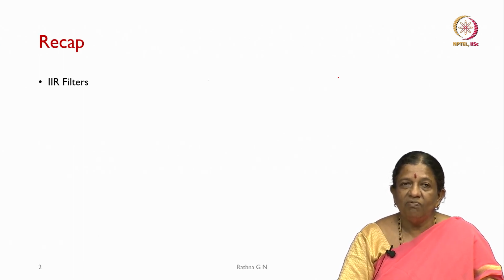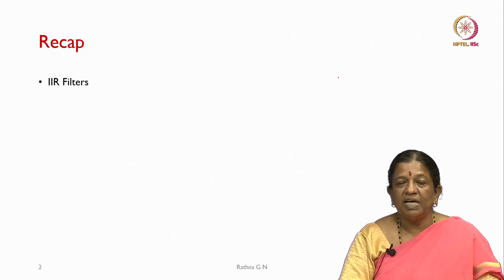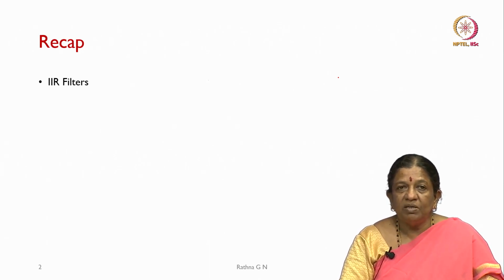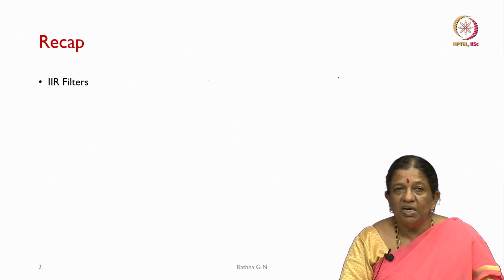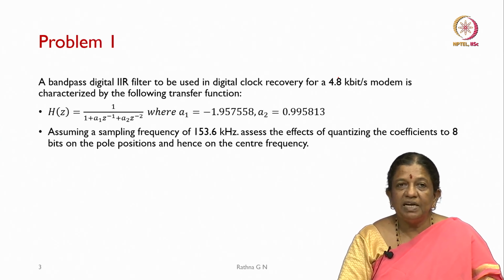That is the reason why we will not use the parallel structure in IIR filter design for these hardware units. Usually we go with the cascade realization, although both cascade and parallel sections have the same effect on the design.